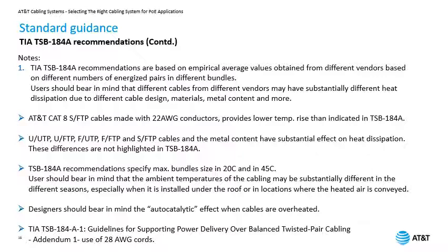In addition, designers should bear in mind the autocatalytic effect when cables are overheated. There is addendum 1 to this TIA TSB-184, which is talking about 24 or 28 AWG cable used in PoE delivery.